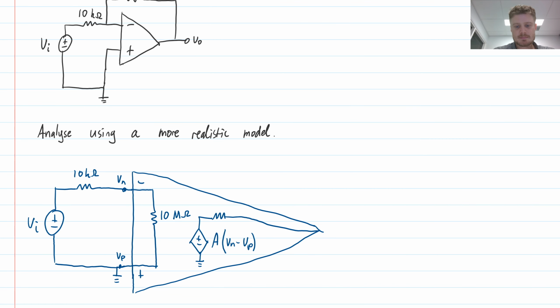So let's go back to our picture. If I have 1 millivolt of difference over here, then I would have 140 volts being generated by my source. So you see this is quite large. So I actually have here that my value of A as a dimensionless quantity is going to be 140,000. So that's the kind of relationship from volts to volts, a gain of 140,000.